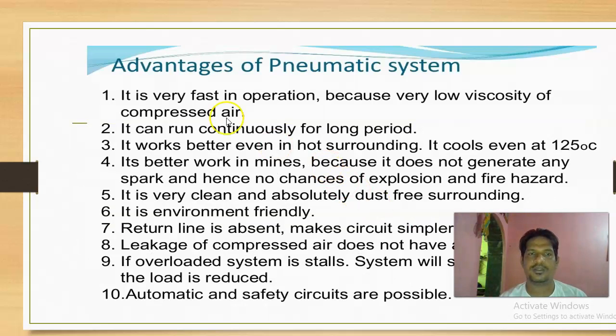So first, as per the outline, we will discuss advantages of pneumatic systems. Why we prefer pneumatic systems. The basic advantage of a pneumatic system is that we use air as the fluid medium. So it is very fast in operation because of the very low viscosity of compressed air. It can run continuously for a long period. It works better even in hot surroundings.